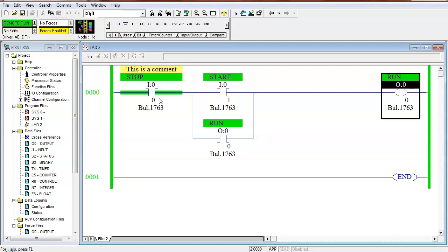But what's really neat is when I buy sensors, all my sensors can have a normally open contact. And if I wanted it to act like a normally closed contact, I would use the examine if closed instruction. And that's what's cool about a PLC. So now I don't have to have all these contacts. I need that sensor to act like a normally closed, but all it gives me is a normally open. Well, good gracious, just call it what? An examine if what? An examine if open instruction. So it's really neat. So it's open, but in your circuit, it acts like a what? In your program, it acts like a closed contact. So that's our first program, guys.